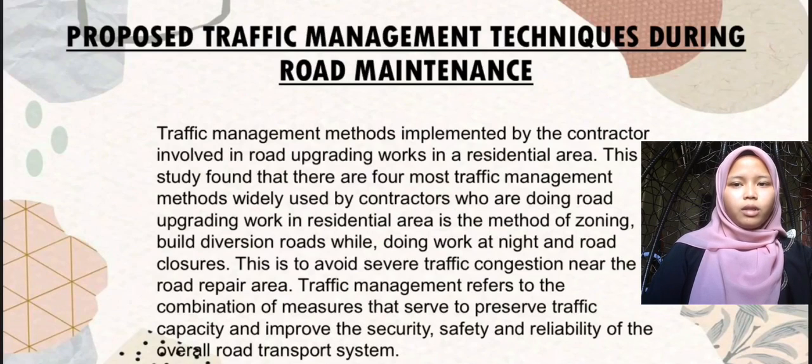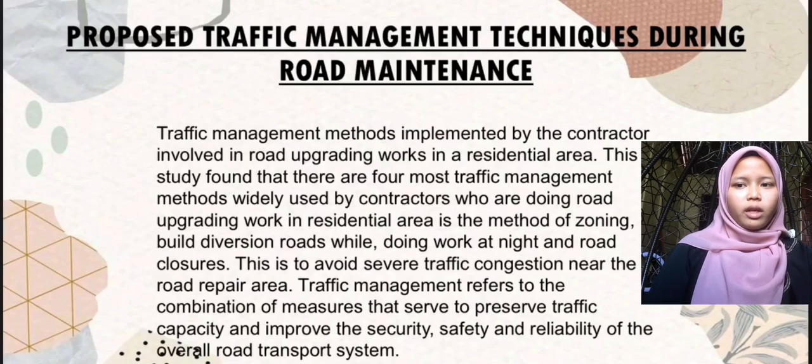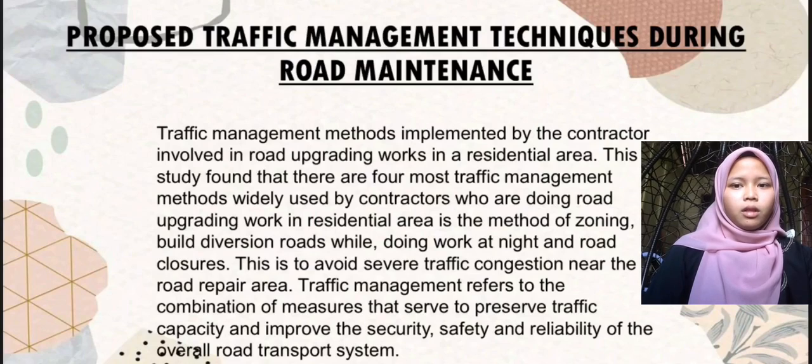This study found that there are 4 most widely used traffic management methods by contractors doing road upgrading work in residential areas: the method of zoning, building diversion roads, doing work at night, and road closure. This is to avoid and resolve traffic congestion near the road repair area.